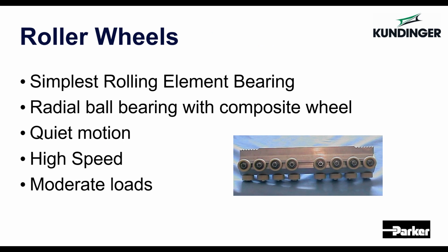Bearings can ride on just raw anodized extrusion without any kind of secondary machining, really keeping the cost down, because at that point the bearing is just an inexpensive piece of silicone impregnated plastic. These are low payload, low speed, also low stiffness and accuracy, but in these types of applications where you're looking at a glider bushing, those aren't really specs that you're going to care about.